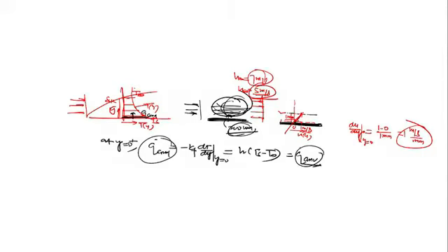Let's say it becomes 1.5 meters per second. Then what about the gradient, du upon dy at y equal to 0? Now the change in velocity is 1.5 minus 0 upon 1 millimeter, and this is 1.5 meters per second per millimeter.